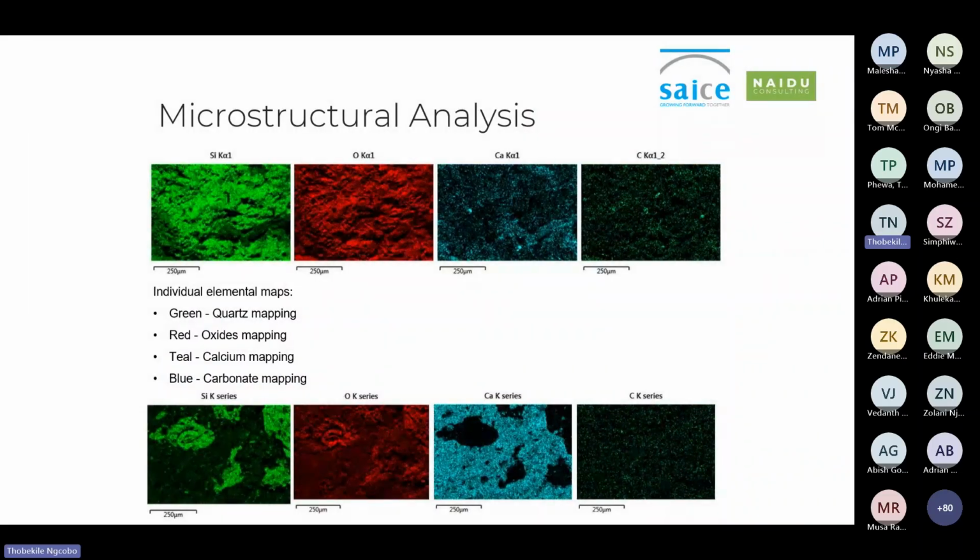The elemental mapping shown on the screen compares the fire-exposed concrete to unaffected concrete. In the unaffected sample, calcium, for example, is clearly present and evenly distributed. Whereas in the fire-exposed sample, there is a noticeable reduction in calcium concentration within 30 millimeters. This reduction corresponds with the loss of calcium hydroxide and indicated a potential decrease in the strength as well as the durability in the surface zone.